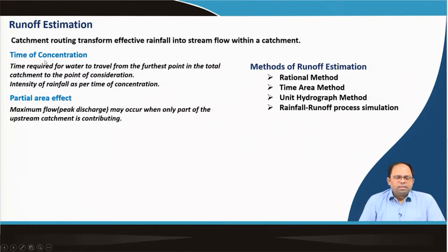Now, we have already discussed the concept of time of concentration, but I will elaborate on it further. It is the time required for water to travel from the furthest point in the total catchment to the point of consideration, or in this particular case, the inlet. Whenever we consider the surrounding area of the inlet, it is the maximum time required for water to start from the farthest end of that area and reach the inlet. But this is direct water that comes to the inlet.